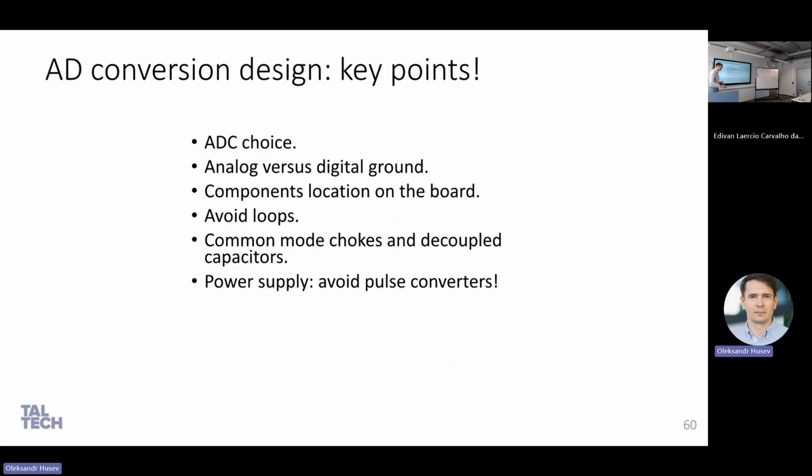I didn't mention it directly, but in most cases it's obvious: for the reference signal in your AD design, never use switching converters for reference voltage because they have very high noise. For that, usually low-noise LDOs are recommended, especially for AD conversion. You can think that you have addressed all issues, but if you don't pay attention to this aspect alone, it may destroy them.